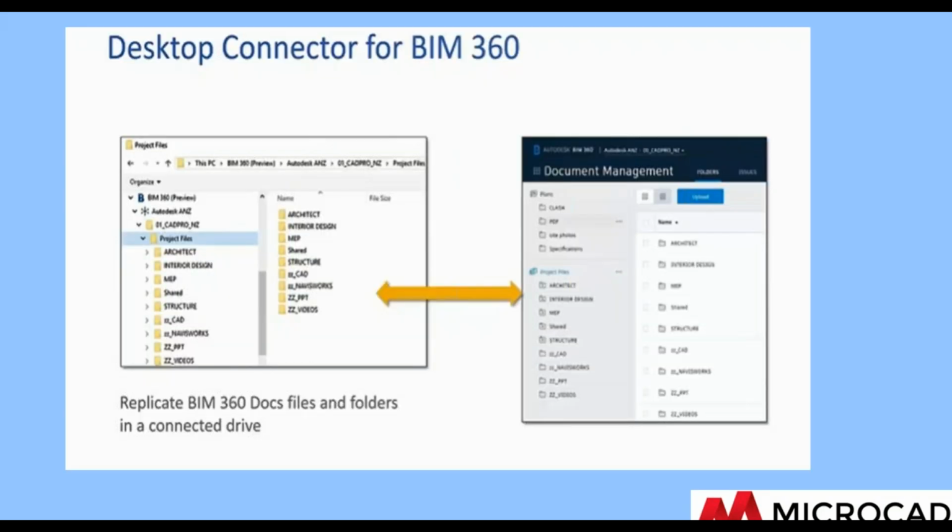All right. We've kind of focused on user experience within Revit and BIM 360, but let's talk briefly about file management. We know that when Revit work sharing creates a local RVT file on your workstation, this contains your changes until you sync it with the central file in the cloud. Same thing happens with BIM 360, and there are other reference files you need to manage.